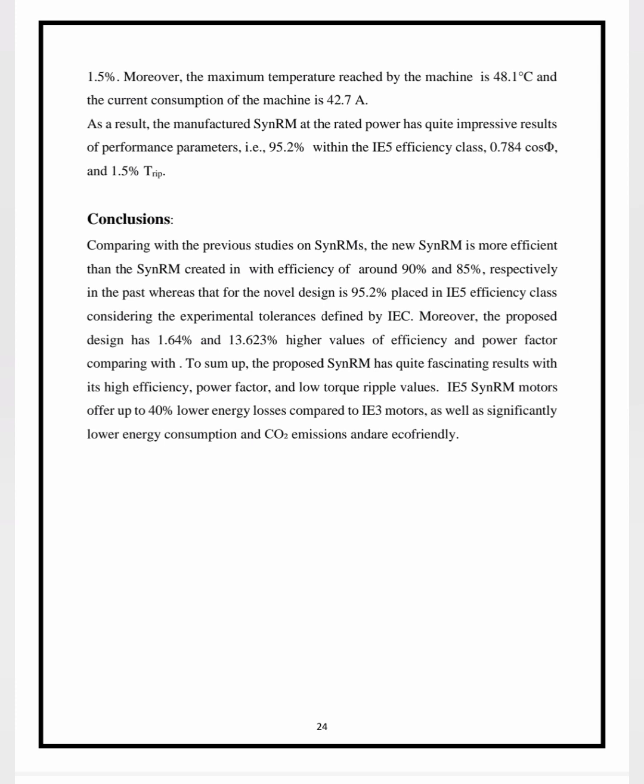95.2%, and it lies under the IE5 efficiency class with 0.784 cos theta and 1.5% ripple torque. So it is a highly efficient IE5 motor. That is why we have chosen it in the modern technology of today's world.